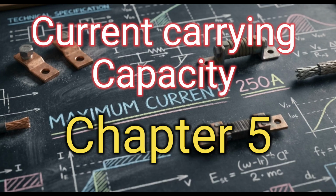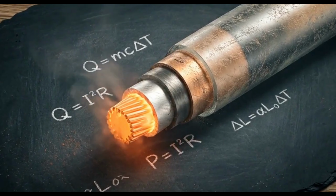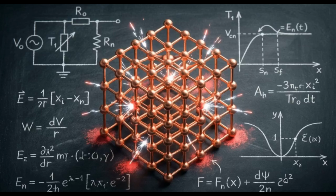Engineering specification sheets define a cable's maximum current with a fixed numerical rating. This value represents a thermal ceiling, the exact point where electrical resistance produces more heat than the surrounding insulation can safely endure. Every ampere of current flowing through a conductor generates thermal energy via I squared R loss. This heat is a direct product of the current squared multiplied by the metal's electrical resistance.